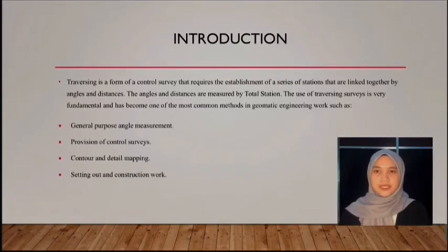Introduction. Traversing is a form of control survey that requires the establishment of a series of stations that are linked together by angle and distance. The angle and distance are measured by total station. The use of traversing surveys is very fundamental and has become one of the most common methods in geometric engineering work, such as general purpose angle measurement, provision of contour surveys, contour and detail mapping, setting out and construction work.